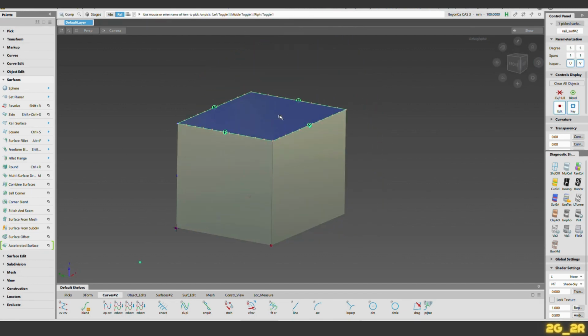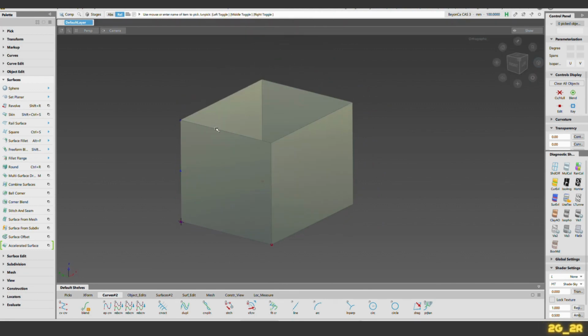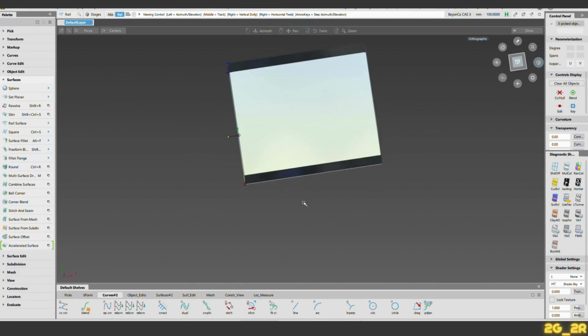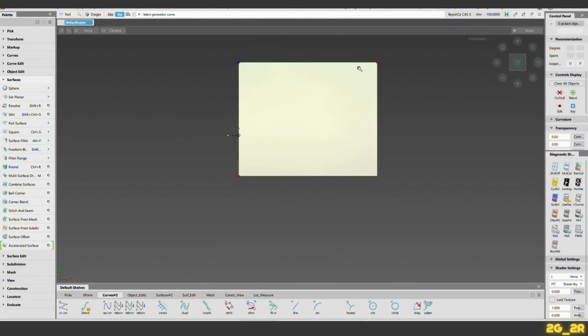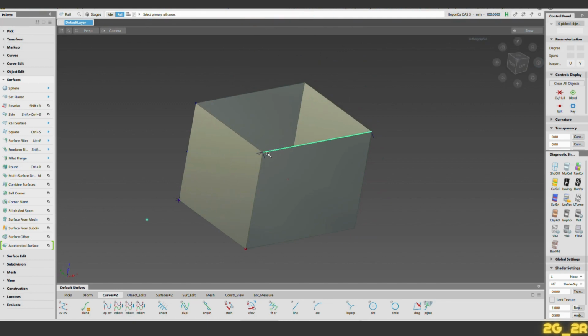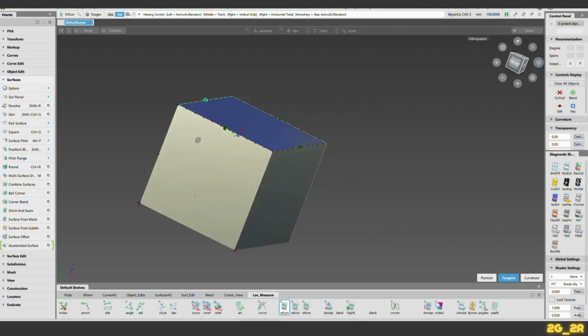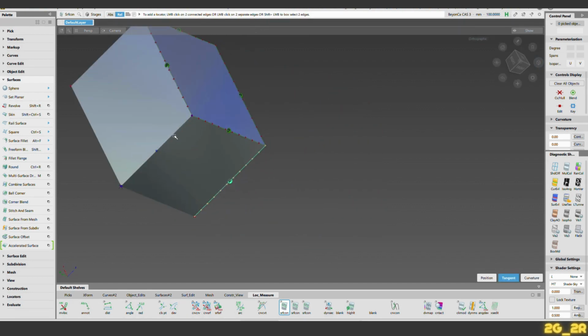Another way to do that would be to build a monorail, because everything is squared off here. So we've got 90 degree angles everywhere. So we can just build a monorail of this edge along this one, similar to the base. And you will see it's a closed volume now. All edges are closed, working nicely.